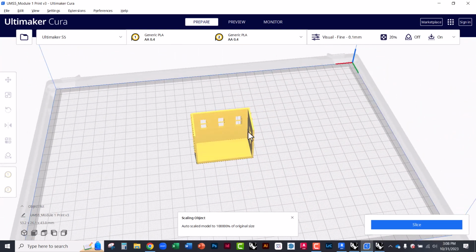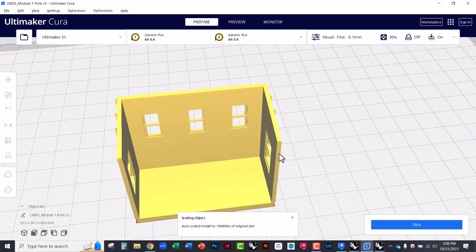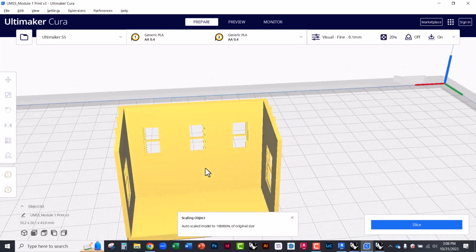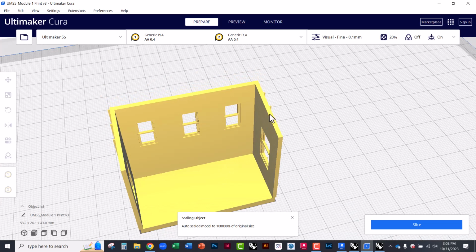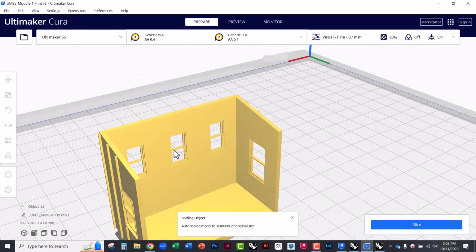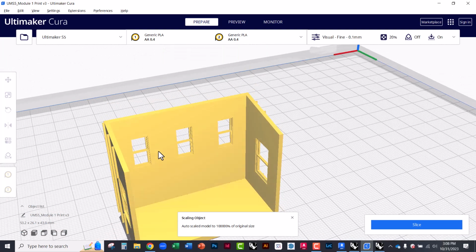But the thing that we want to make sure is that the wall thickness is still within the minimum thicknesses for this print, right? We want it to be within tolerance. You can only print a certain width. Every printer has different requirements for how thin the walls need to be. So you can't make it paper thin. But at 1/8 inch scale, the overall wall thickness is about 6 or 8 inches, so that means we're a little over a 1/16 of an inch for the walls. So we're good. We know that the thickness is okay.